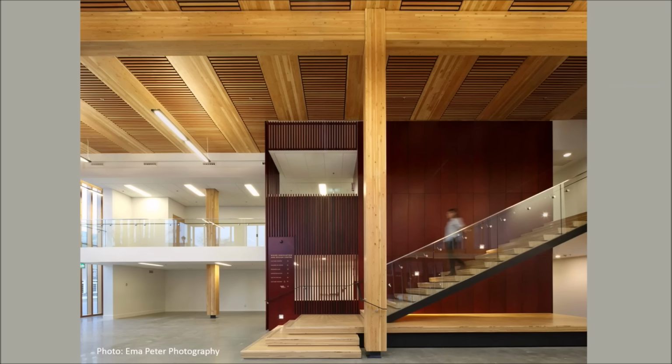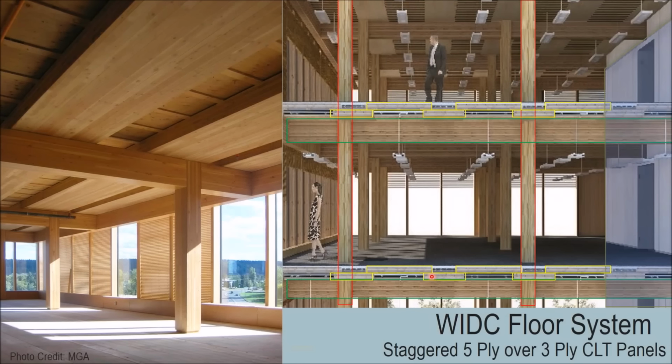What is different is that it has a 2-layer CLT floor deck where you have 2 different layers of CLT all spanning in one direction together, but they're staggered to create chases on the top and bottom for systems, so that we have a chase for electrical systems in the floor, and then a chase for fire sprinkler lines and lighting and electrical in the ceiling.